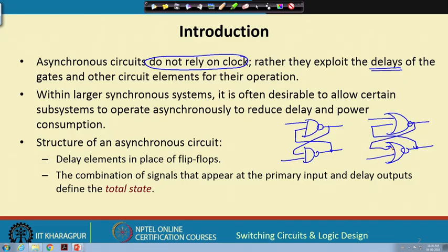While we were discussing flip flops, we saw this kind of 1-bit latch design. Now, you see, this circuit in itself is a sequential circuit, because it can store some data. So, once I store some data, 0 or 1, as long as I am applying 1 1 here, it remembers this value, because 1 and 1 gives 0, it remains 0, and 0 and 1 gives 1, it remains 1.